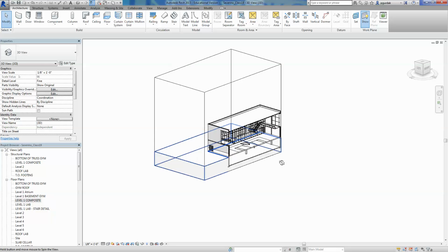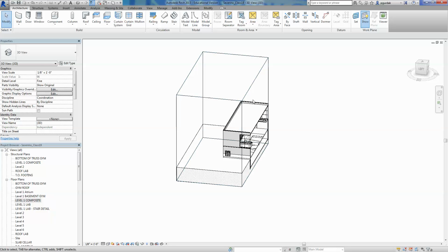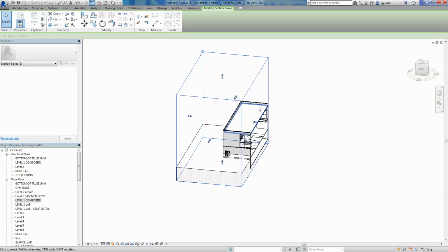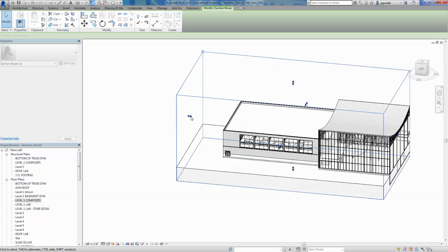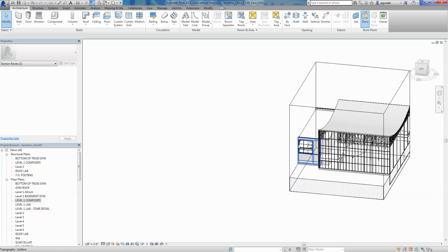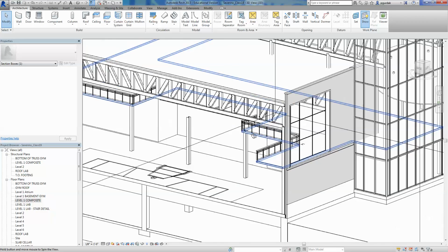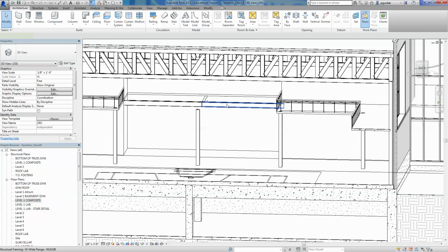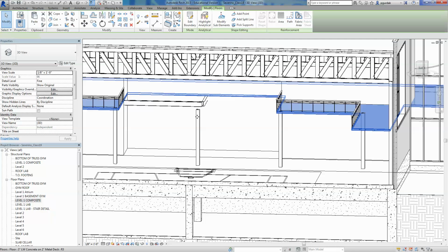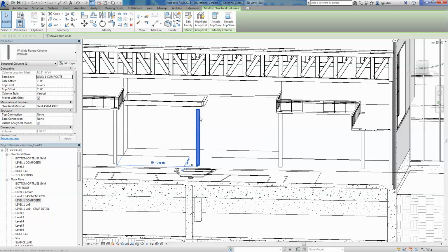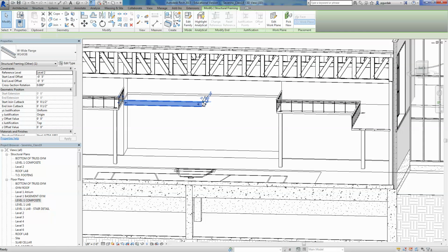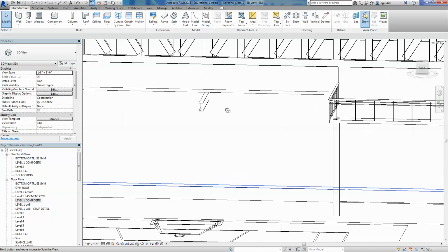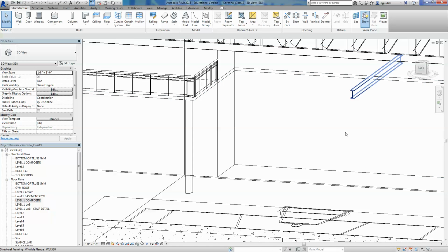I'm going to start the stair because it's a little more tricky, and from there we jump to the atrium. It's going to be much faster. The stair goes in this space, so we need to also clean up a little bit the beams, because obviously these columns are in the middle of the space required for the stair.